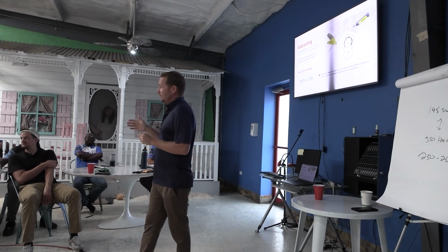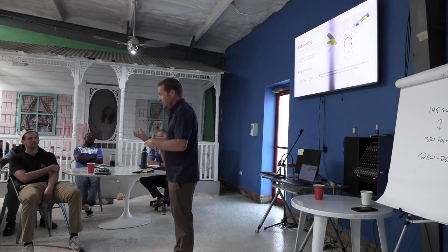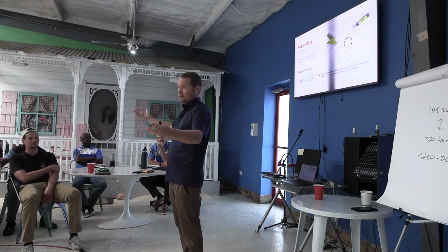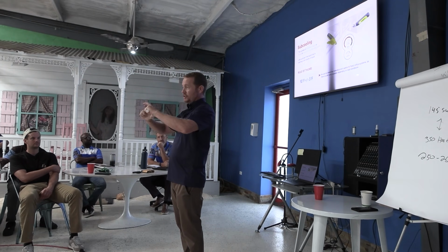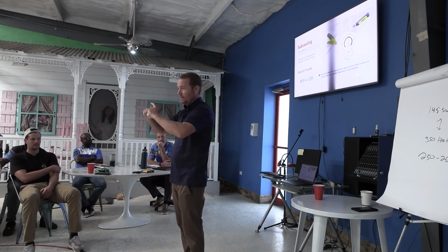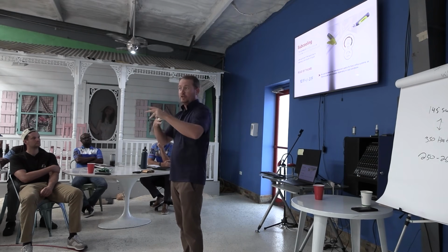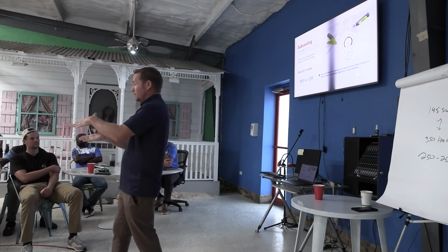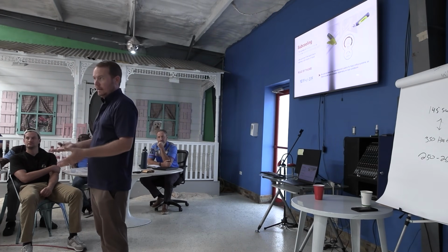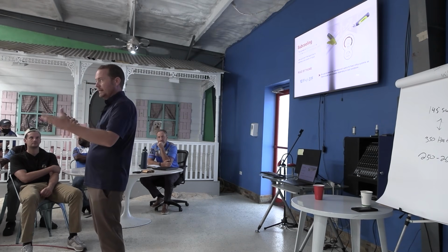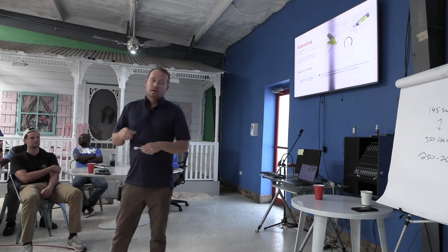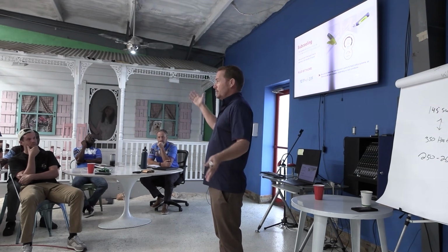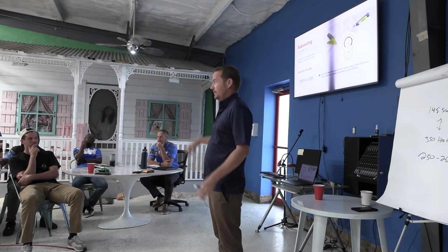So a lot of this stuff, everything that we do that's pressure related, because that's what we're doing. All these calculations we're doing on the air side and on the refrigerant side are pressure related measurements. They rely on a properly functioning heart. And if that heart isn't properly functioning, all bets are off. Now, we can say, look, my compression ratio is really low, like really low. That's an indication of a compressor that's not pumping properly. That's how you actually tell. Like, oh, I don't think this thing's pumping. You listen to it, amperage, everything's like, yeah, this thing's not pumping. Same thing is true of the blower, though. If your blower's not pumping, if it's not moving enough air, your pressures are going to be really low because it's not moving.